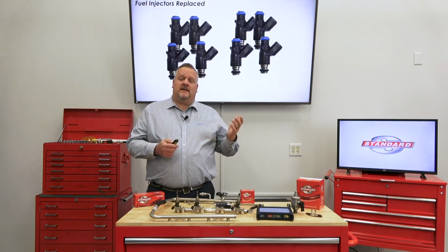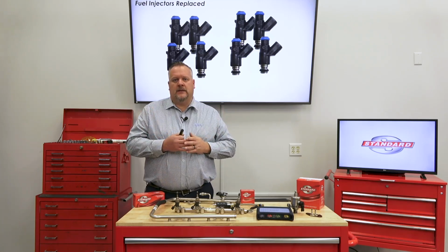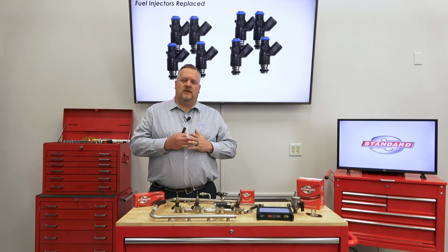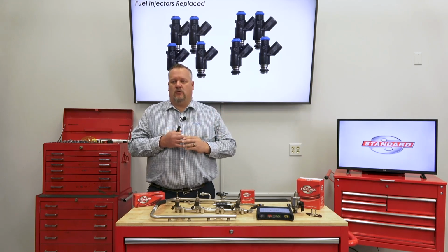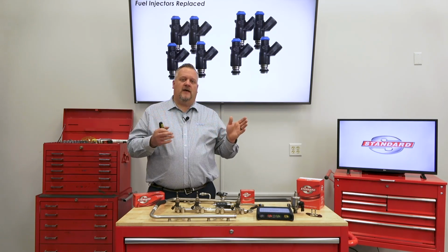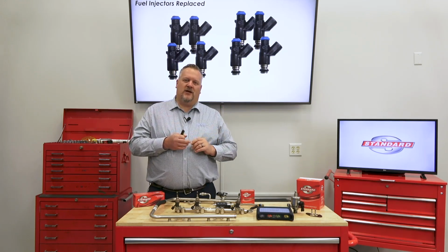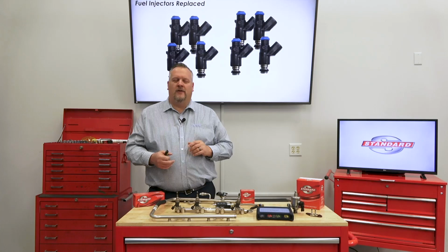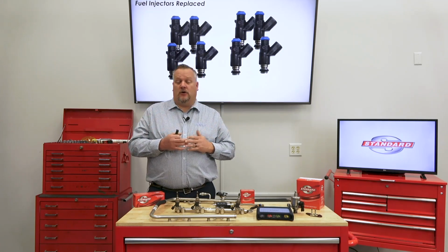And so based on the mileage of the vehicle here and some of the other stuff, the fact that the rail was coming up, this particular customer said, you know what, I'm fine, we're gonna go on a trip with this one. Let's go ahead and replace all 8 fuel injectors at that point. This way we're ensuring that they've got a nice balanced system. How many times haven't you seen it where you replace one injector and 2 weeks later another one goes out? They've all opened and closed just as many times there. And so this is a great recommendation.